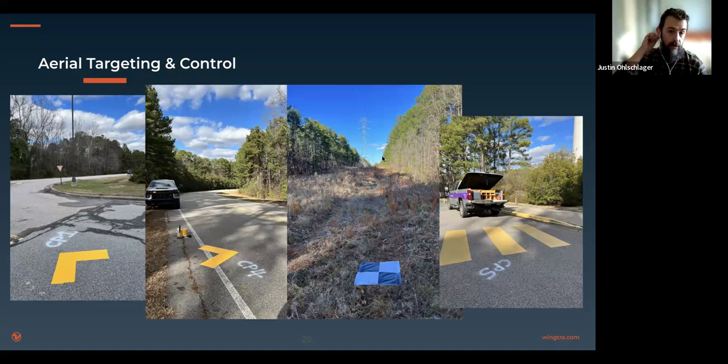Yeah, so at McKinnon Creek, when we deal with any type of aerial LiDAR, whether it's manned or unmanned, within our workflow is some sort of strip alignment. In this case, there wasn't a lot of strip alignment needed, but we went ahead and ran it anyway. As you notice, going from 2 centimeters to about 1.7, for some people, that's not a huge difference. But for us here at McKinnon Creek, we have the ability to do that, so we do that for most of our projects.